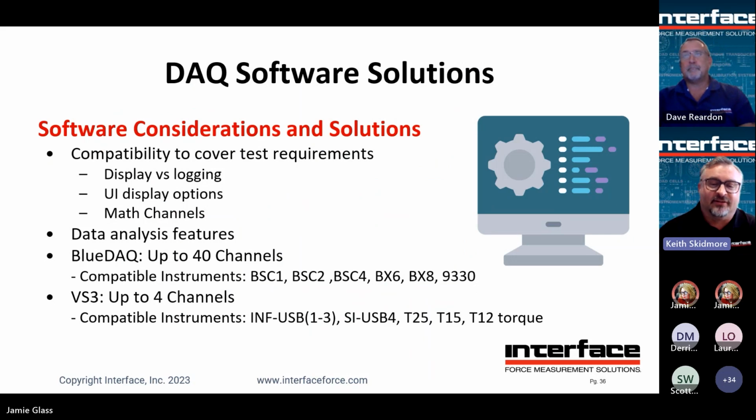Say we have 3 different USB modules that use different kinds of software. Well, which one's the right one? Well, is it for displaying, or do you want to log primarily? What do you need available in the display? Do you want to be able to configure it, or are you okay with just whatever it is? Do you need math channels? Math channels could be super simple, like A plus B equals C. Channel 1 plus channel 2 equals the total. Or you could do derivatives, or say center of gravity calculations, or calculate force vectors with multi-axis sensors. So the sky's the limit, but you need to understand what you need to do before we decide which package is appropriate.